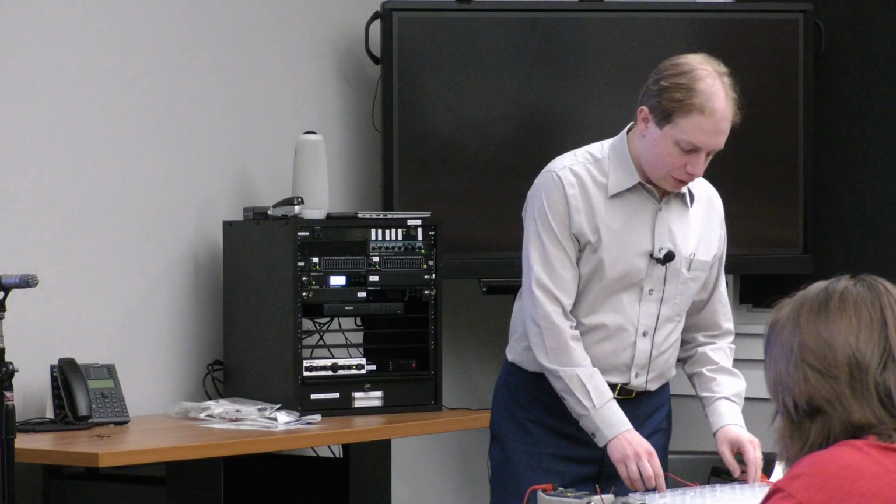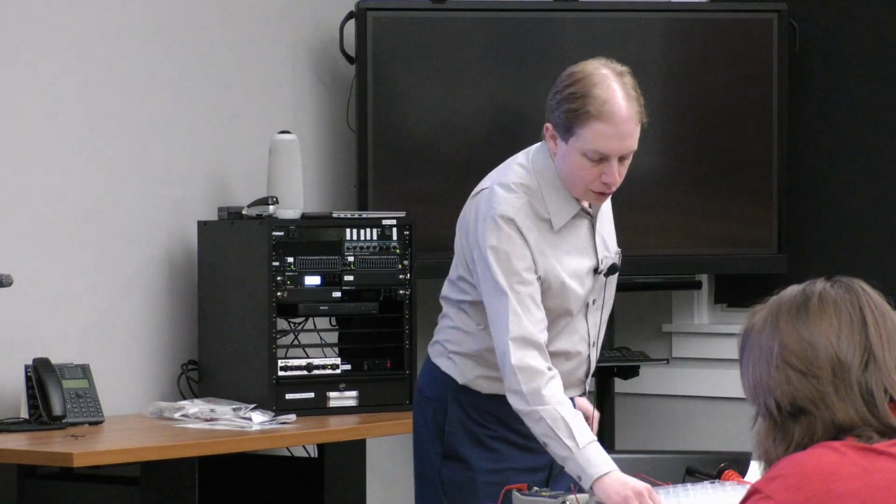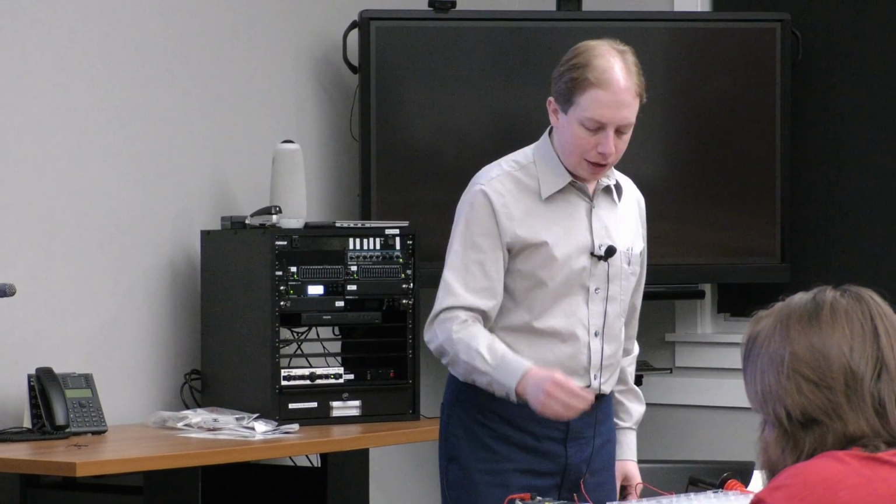And if you're talking microfarads, generally you're talking bigger electrolytic capacitors. If you're talking picofarads, you're usually talking like little disc capacitors, ceramic capacitors, mica capacitors. So what do I mean when I say electrolytic, disc, ceramic, mica? It refers to the dielectric inside the capacitor. Capacitors are one of these interesting devices where there's a huge array, kind of like breeds of dogs. You get little Chihuahuas versus St. Bernards versus sheepdogs. There's vast differences, and you'd hardly recognize a Chihuahua compared to a sheepdog, but they're all canines.